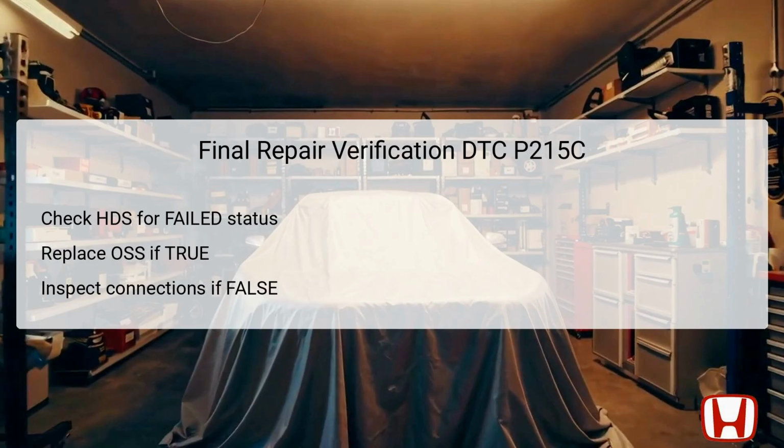In such cases, technicians should inspect for potential poor connections or loose terminals surrounding both the output shaft speed sensor and the powertrain control module, PCM. Re-establishing secure connections can sometimes resolve mysterious or elusive error codes. If conditions allow, testing those components under the same parameters that initially triggered the error can also help in understanding the issue's nuance and connectivity logic.